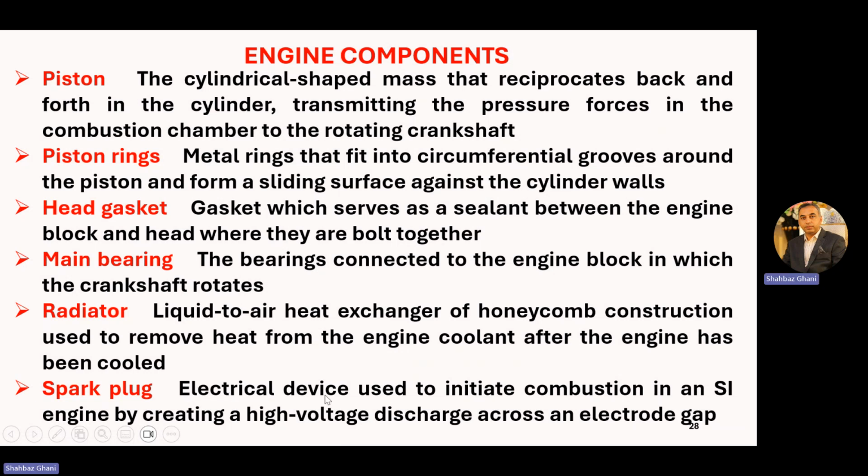Spark plug. The electrical device used to initiate combustion in an SI engine by creating a high voltage discharge across an electrode gap. Spark plug is used in an SI engine. Basically, at the end of the compression stroke, the spark plug gives the ignition to that air fuel mixture with the help of that spark, and the ignition leads to combustion. And remember, the spark plugs are always in SI engines, not in CI engines.